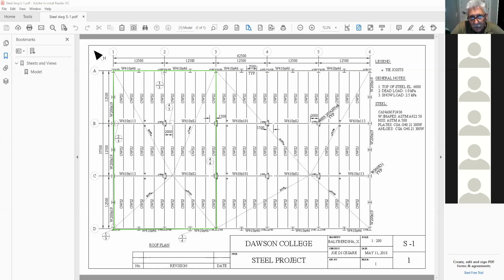2%. 5%. Oh, that's awkward. See, it's minimum 2%, guys. On the city sidewalk, they put 5% because sometimes the sidewalk settles. They want to make sure the water still drains off the surface. So next time you're walking on the city sidewalk, go to the edge and take a look, and you'll see there's about a good 5% slope in the sidewalk.